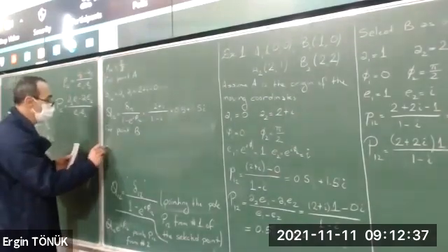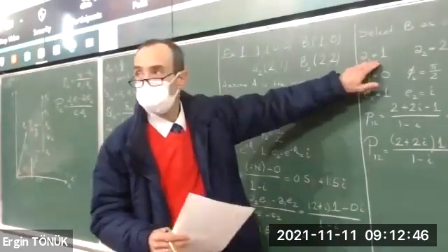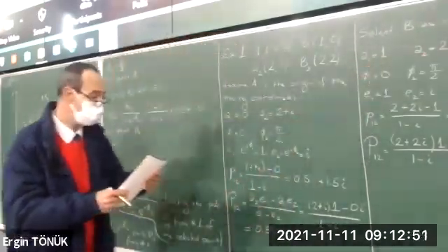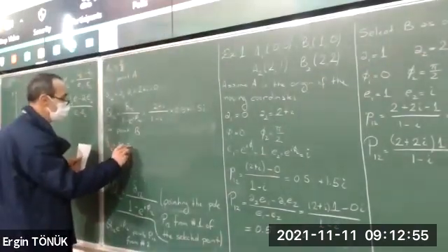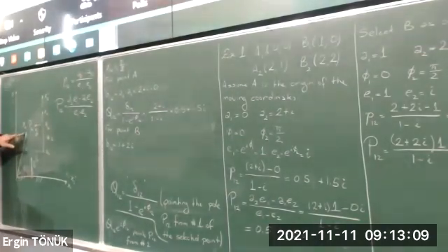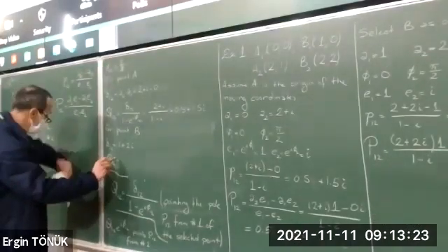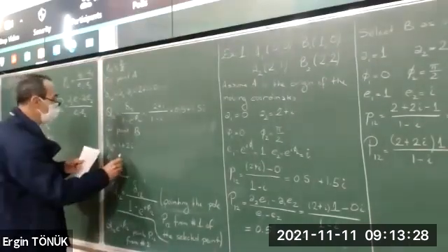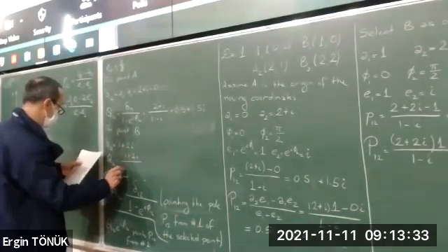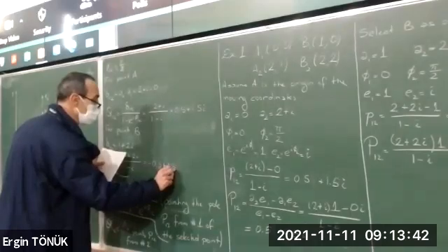This time, my displacement vector will be different because I will be using for A2 this, A1 this, okay? So I'm going to subtract from this. So it would be 1 plus 2r, okay? Displacements of different points are not invariants of the motion. It depends just on the point you select, and actually for the pole, the displacement is 0. We derive this first equation using that property, okay? So that's not surprising. Then Q12 becomes delta 1 to 1 plus 2r over 1 minus r, and this yields negative 0.5 plus 1.5 r.